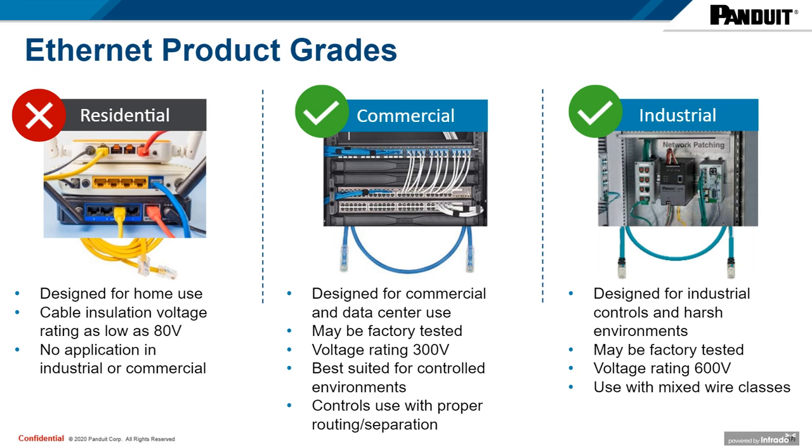We would prefer to have a cable that is made for this space as well, an appliance wire type jacket, and the quality of the cable as well, including the ability to have shielding in that cabling that mitigates the noise that happens on the plant floor.